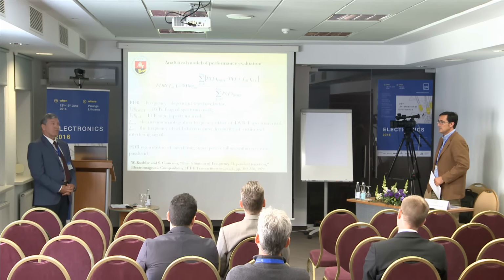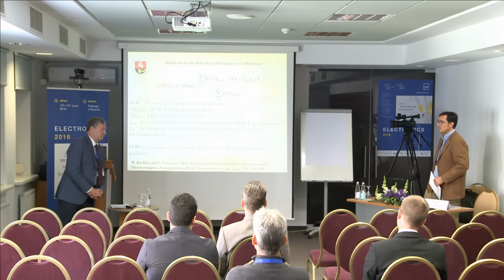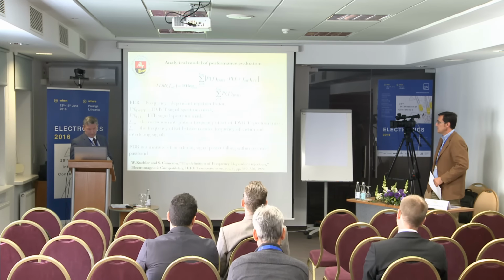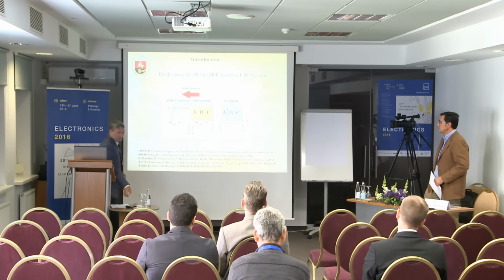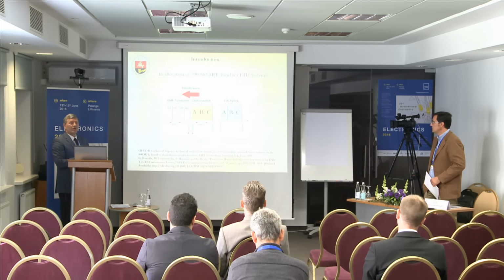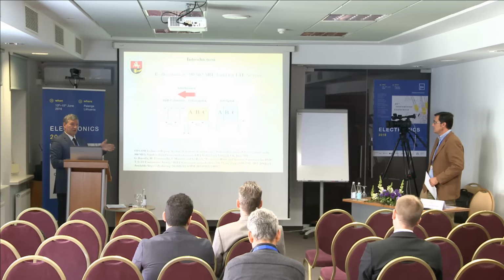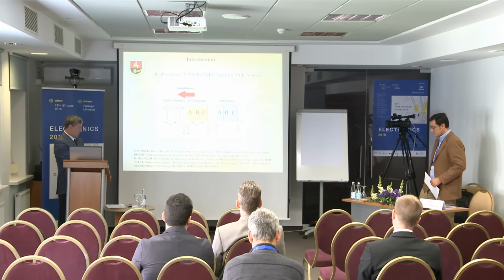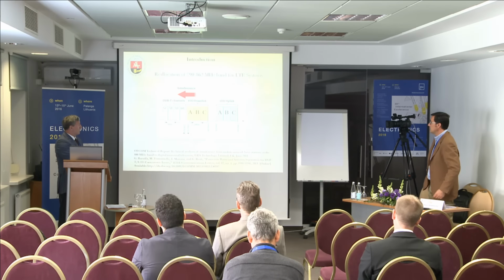And the second short question is, what is the physical reason for the interference? Maybe intermodulation products? The physical reason of interference is the channel edge distance between LTE and DVB-T.